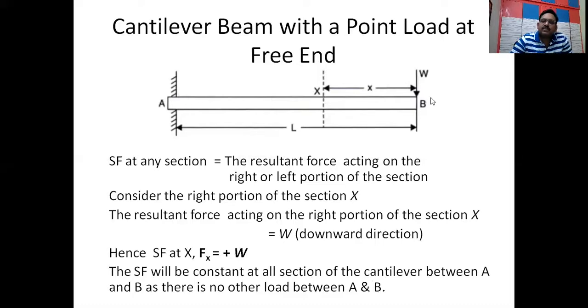Therefore, the shear force will be that force only, acting downwards, and there is no other load between A and B. Therefore, the shear force will be constant throughout the span from A to B. This is what we have.